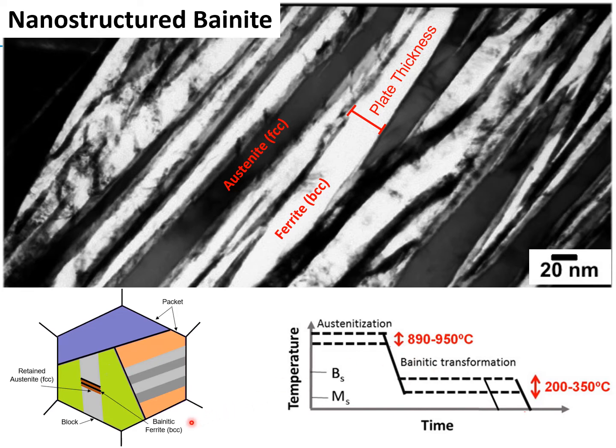It's been stated that the nanoscale bainitic ferrite features that are achieved through the relatively low temperatures bring a high value of strength to the microstructure, and the ductility is due to the composite behavior of the microstructure coming from the presence of retained austenite, particularly the film-like retained austenite features. This schematic illustration of a grain will be explained further in depth later on.